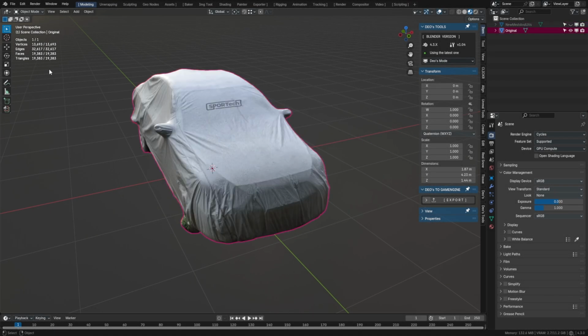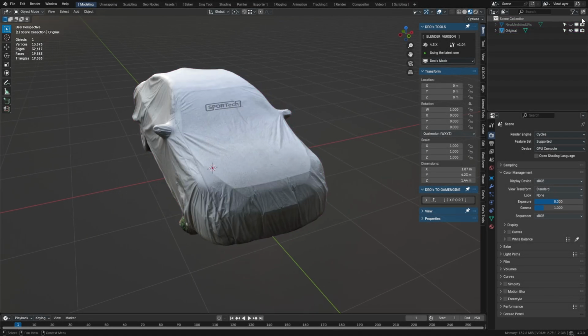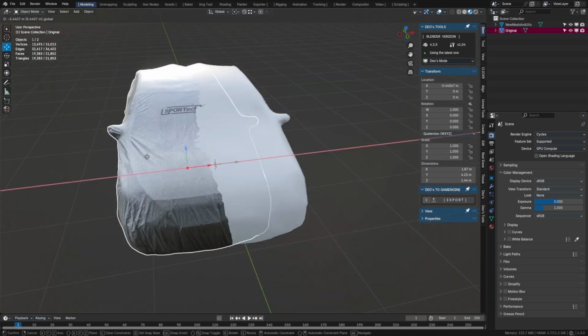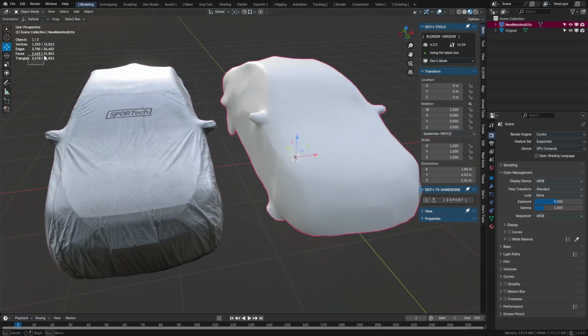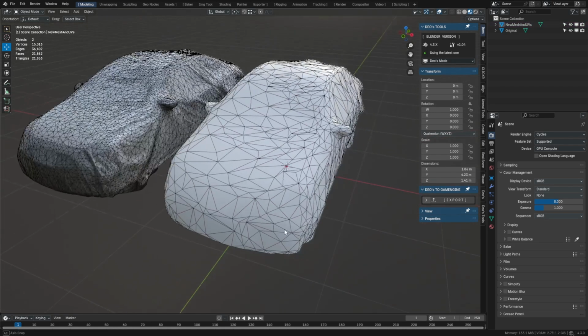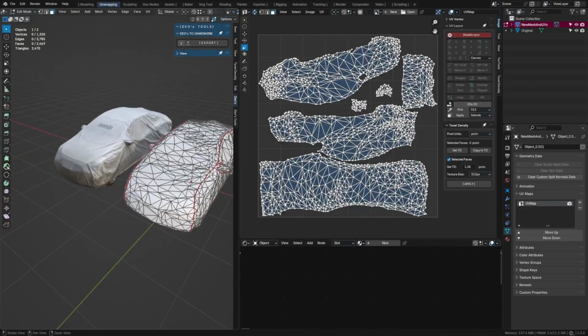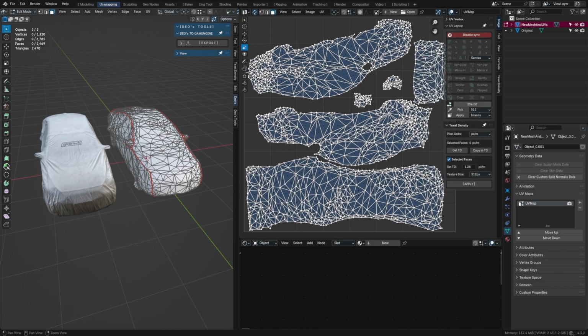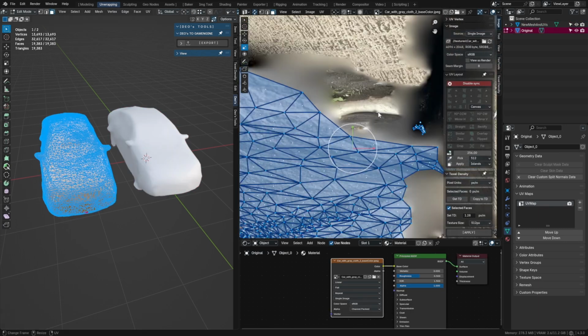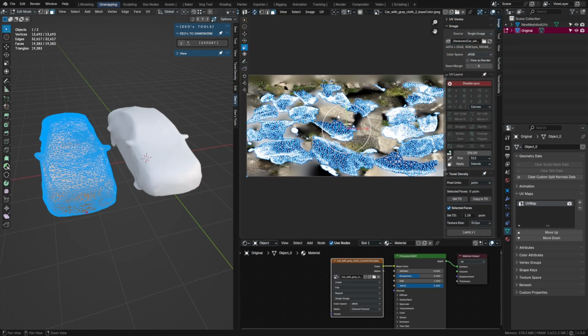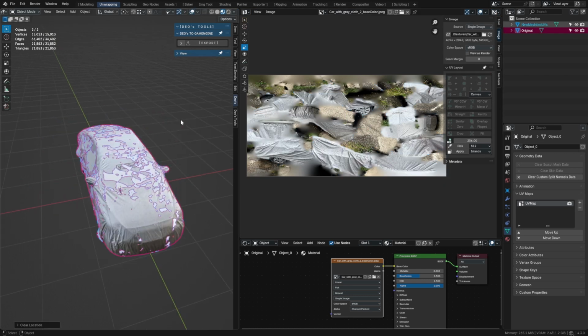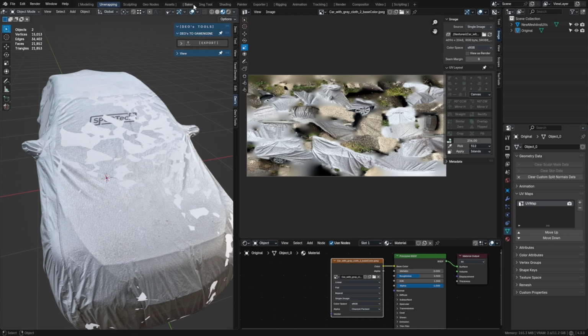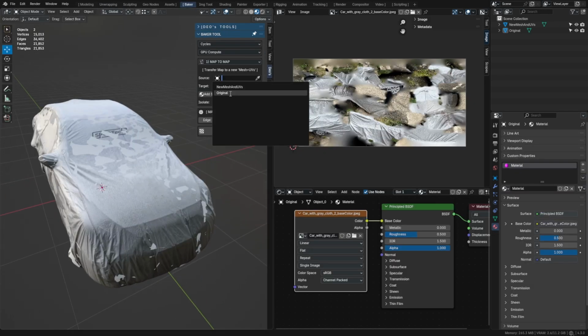This model comes from photogrammetry and has more than 19,000 triangles. To improve performance in video games, it's important to optimize the model by reducing the number of triangles and improving the unwrapping to maximize the coverage of pixel information. And use a big 4K texture. Now, with the new model topology and a better optimized unwrapping, you can load the source mesh and the target mesh to bake the new 2K texture.